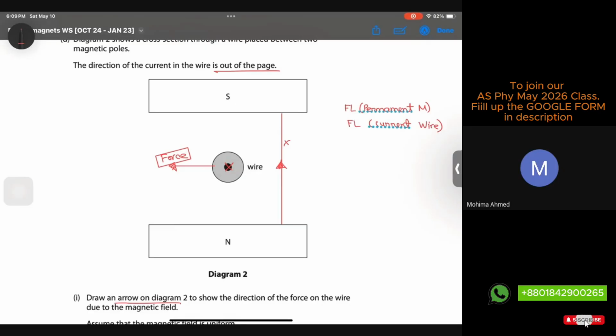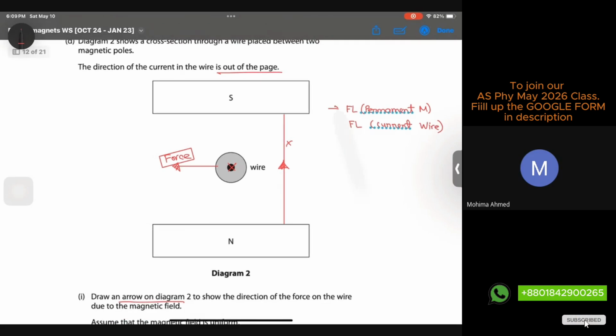Now, if I want to reduce the force from another point of view, this one was for the distance between the permanent magnet being increased. But the other one could be that I reduce the magnetic field lines of the current wire, right? How can I reduce the magnetic field of my current wire? By allowing a very small current to flow through the wire. A small current will produce smaller field lines and therefore decrease the flux linkage and again decrease the force. Is this clear, Amla?